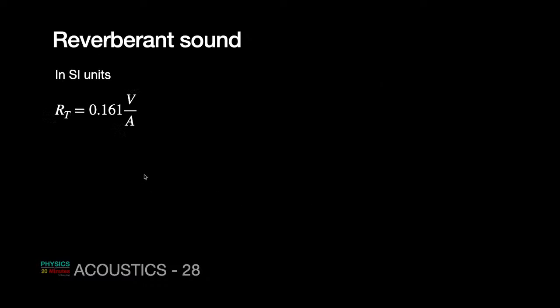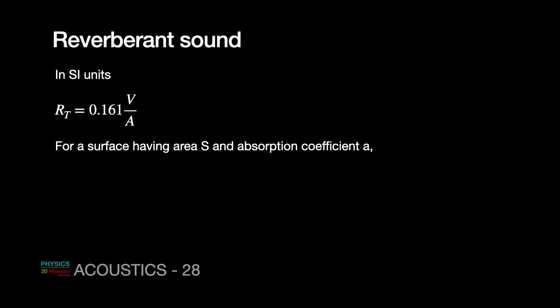In SI units, reverberation time is 0.161 into volume upon area, provided all the surfaces absorb the same fraction of sound. If the surfaces absorb different fractions of sound, then the formula gets a little more challenging.